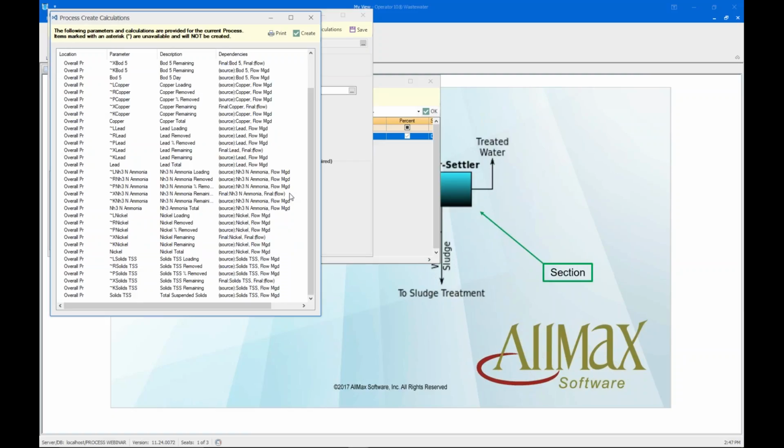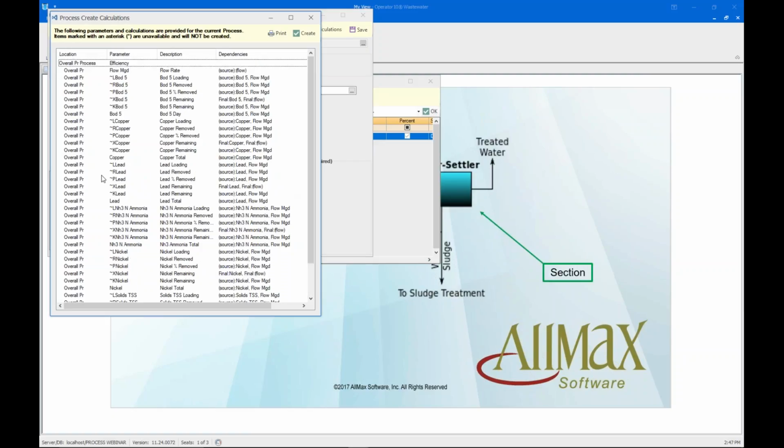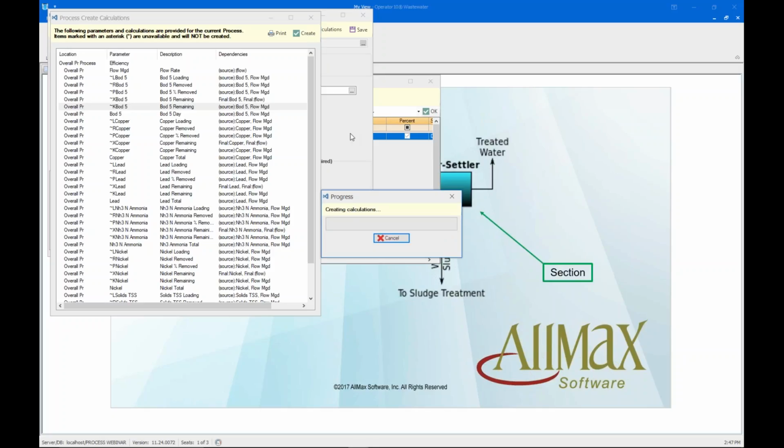percent removals accordingly. But the thing that's going to be nice on this is I'm also going to get, because it is an efficiency, kilograms at the effluent as well. Now, the reason why we do kilograms is that some states, the state of Ohio for example, are required to track the kilograms in the effluent. That's one of their permit limits. So with that, it will give it to us without having to write any formula for it. But this here is based off of just the way we set it up. This is all based off of just the domestic flow coming in.